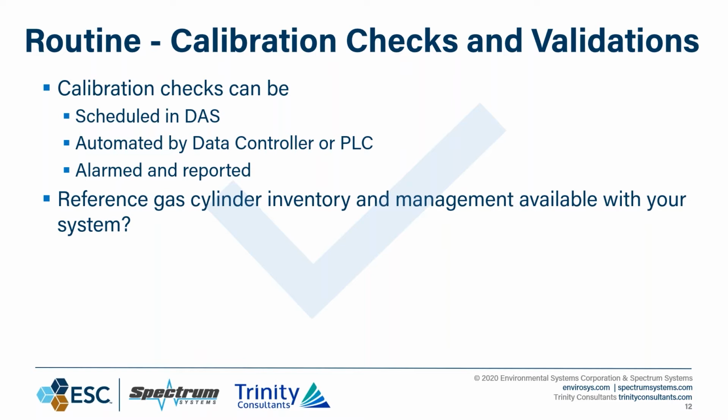The other thing you might want to check in your DOS is to make sure your calibrations and the schedule for when the calibration is being performed matches your permit and also the subpart that you're applicable to. Part 60 and Part 75 have different calibration routines and different requirements. Part 60 is 24 hours, Part 75 is every 26 hours. The DOS can be set up to do those things, but I've seen it so many times where calibrations were set up as a one-stop shop, and it really wasn't addressing the regulatory requirements the way it should.